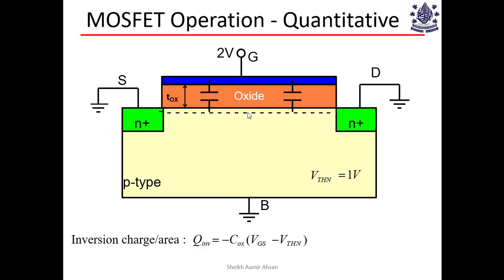Now, again, this brings me to this point that we started with this premise that threshold voltage is defined by that voltage where the inversion charge is the same as the bulk charge, right? So typical number 10 to the power 16, if the doping here is 10 to the power 16. That is equal to the bulk charge, but that is not significant. That is actually very small.